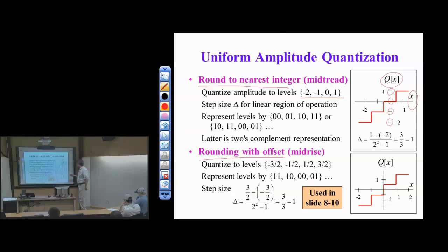If the input to the quantizer falls inside this range, where we have more or less a linear response, we call this the linear region of the quantizer, and we can approximate the input-output relationship with a scalar gain, and we'll do this in lecture 10 with data conversion.